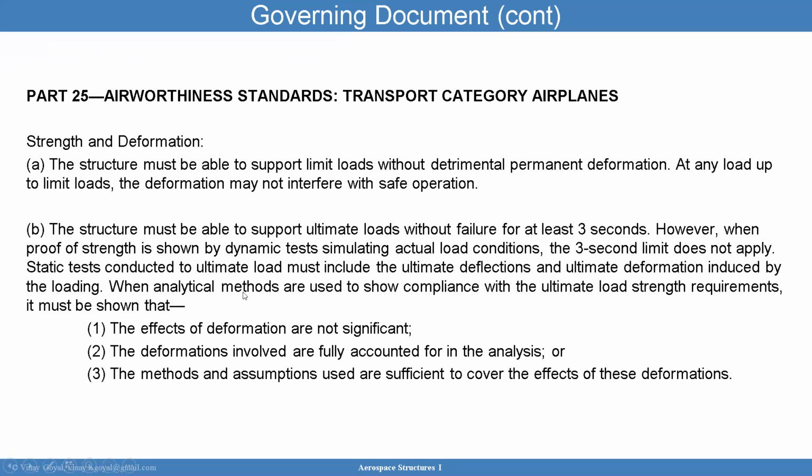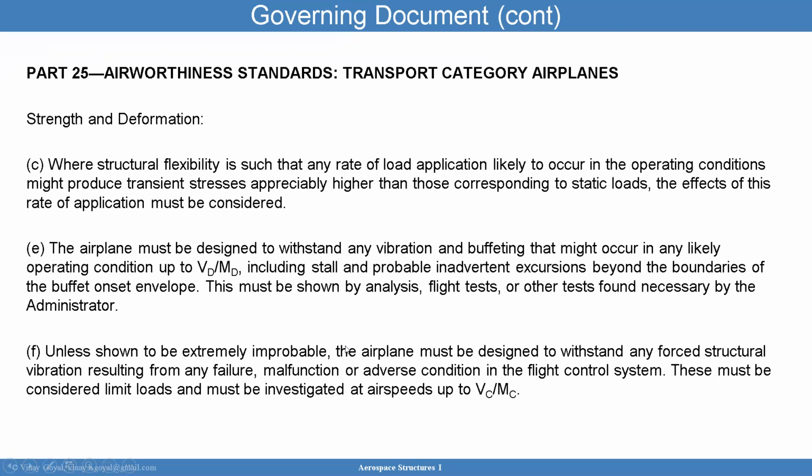Static tests conducted to ultimate loads must include the ultimate deflections and ultimate deformations induced by the loading. And when analytical methods are used to show compliance with ultimate load strength requirements, it must be shown that the effects of deformation are not significant, the deformations involved are fully accounted for in the analysis, or the methods and assumptions used are sufficient to cover the effects of these deformations. Again, very important here, quite consistent with the European standard.